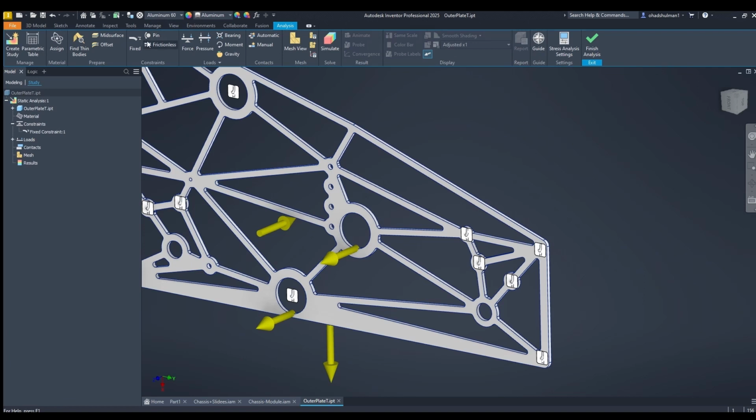Usually if a part can pass 1000 newtons without being hurt, then I can send it to manufacturing, because a normal robot won't really apply 1000 newtons. So that's what I recommend.